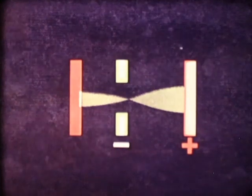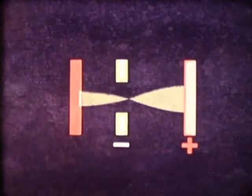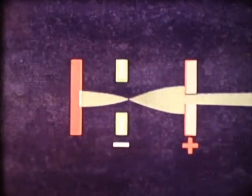The speed of these electrons in the direction of the anode is, of course, very high, and by making a small aperture in the anode, a number of these electrons will be shot through it. In this way, an electron beam is produced, which is used to scan the signal plate.